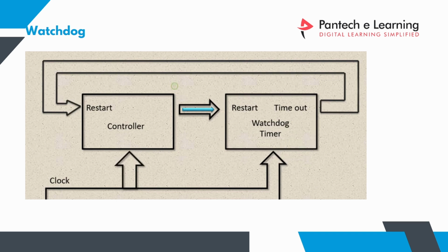So while creating our project for smart agriculture, take a scenario where my pump is not running. At that time I have to reset the controller, right? The user can't go to the farm and reset it. So the controller should understand the loop and reset itself automatically. For that purpose only we are implementing this watchdog timer in the controller.